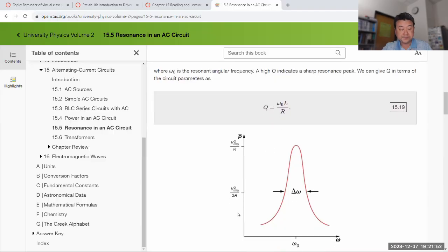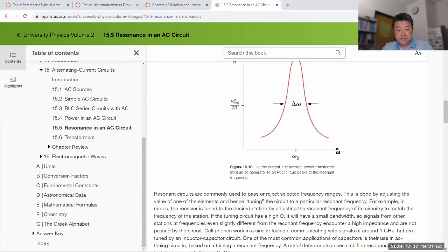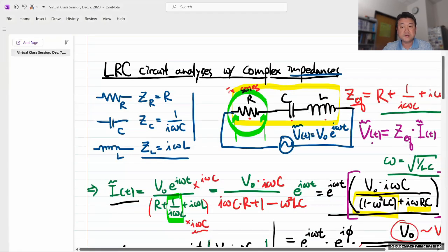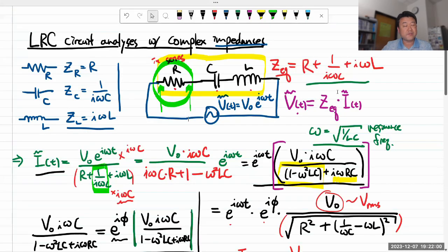And what that means is when you are working with a series LRC circuit, you have to balance these two practical things. In order to be able to measure that resonance behavior and give it proper interpretation, you want this R to be reasonably large. But as this R gets larger, it'll make your Q factor, quality factor, lower.